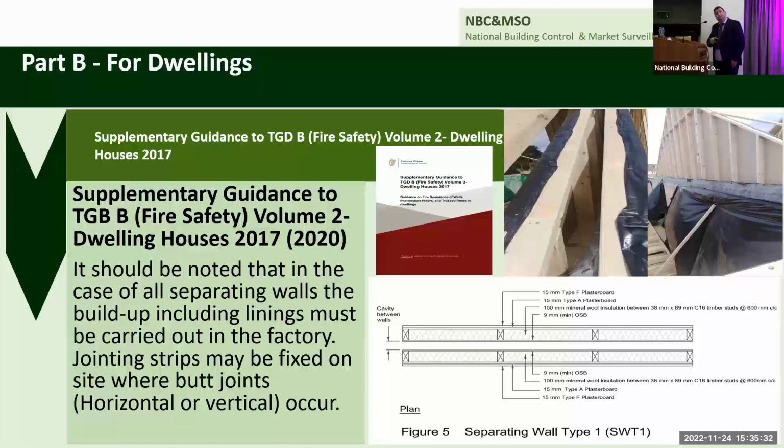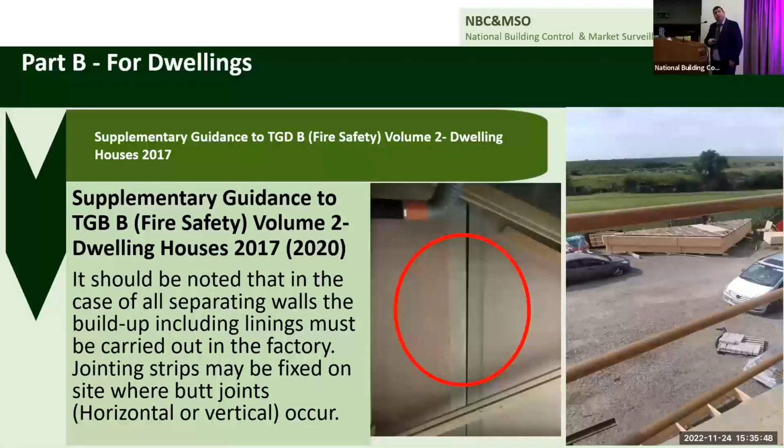And this was a timber frame party wall already lifted on site, and they forgot to put in the OSB board either side and the mineral wool in it. You can see it here. It had to be mineral wooled and sheeted. It couldn't be done on site, so it had to go back to the factory. A whole day wasted because they didn't implement the right thing. Remember, when they're going on site, who's checking to see that that's completed?